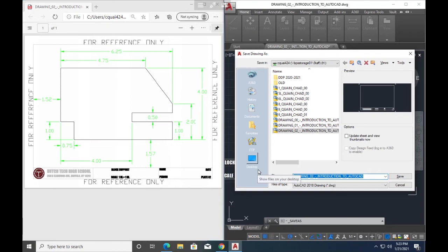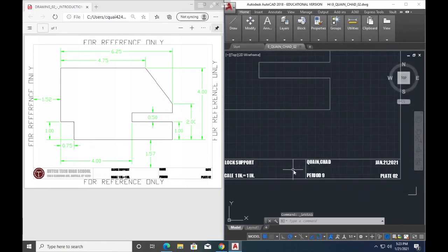Now, one thing that I should probably do, watch this. Instead of having to type everything in, I'm just going to select on one of my old texts. Click here. Click save. Now, one of the things I probably should do, and I didn't do it for this drawing, is I should have turned autosave on. So remember, autosave is AUTOSAVE, enter. And I changed the number to 1 and enter. Now my autosave is set so it resaves every 1 minute.